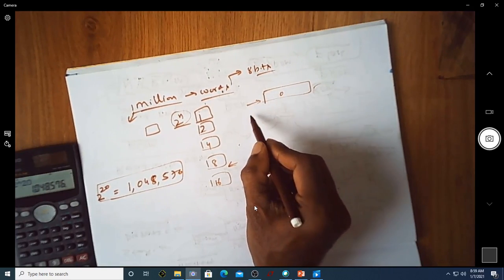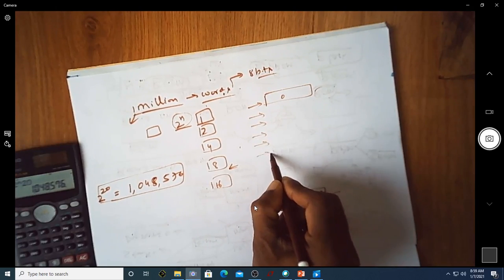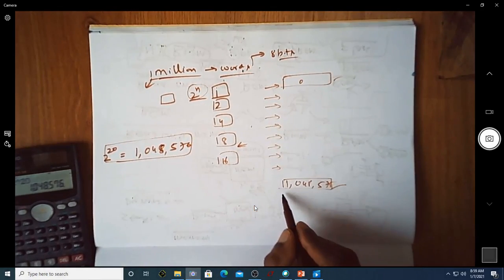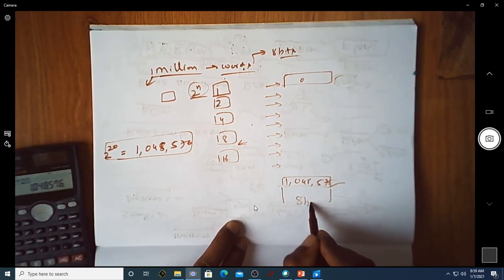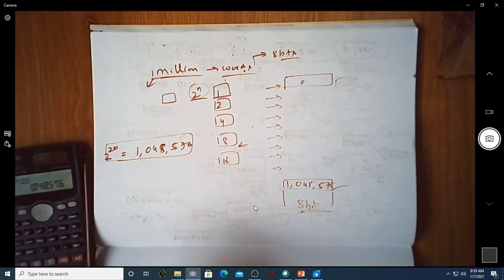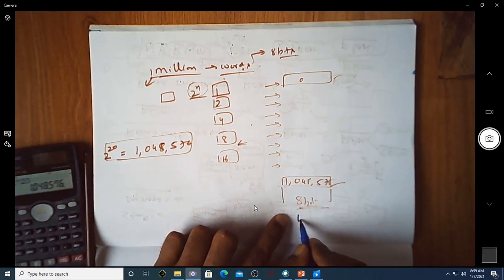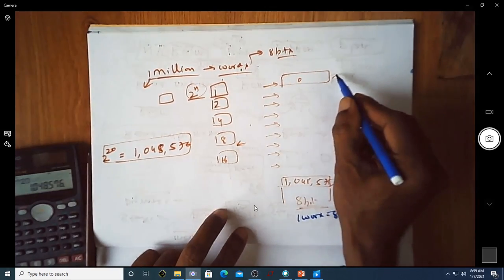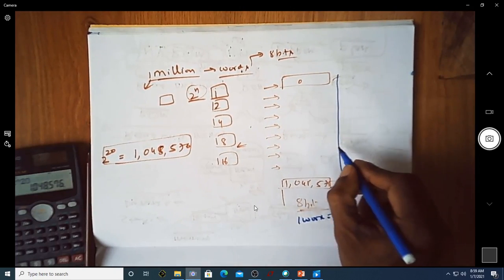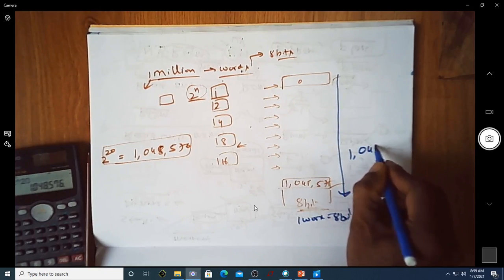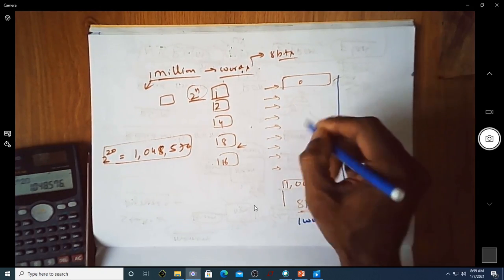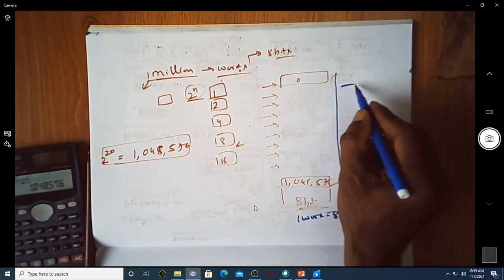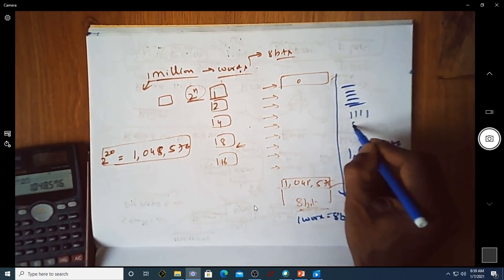You would need that many address lines if you are not using a decoder. This is 8 bits wide, because we are looking at the bits of one word, and one word is 8 bits. But vertically you have 1,048,576 locations, while horizontally you have only 8 bits.